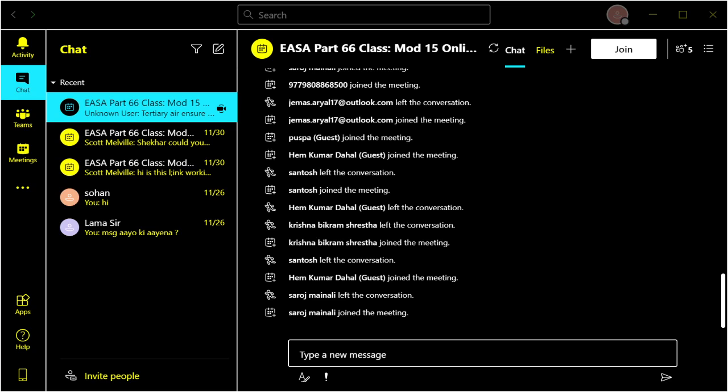Yes, you'll have a smoky exhaust, but we can live with that short term to sort the problem out. But if you get fuel in the oil and it goes to the bearings, that's a lot different. So the PMV, the pressure maintaining valve, always ensures that the oil pressure in an FCOC is at a higher pressure than the fuel, and that goes for both systems.